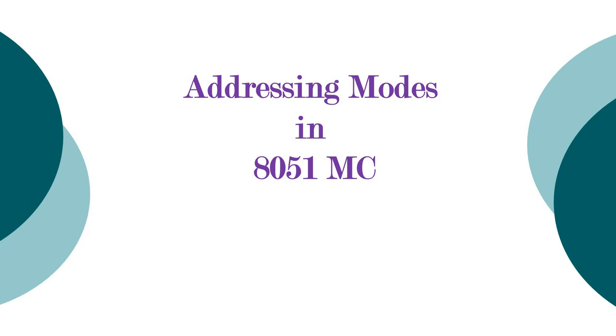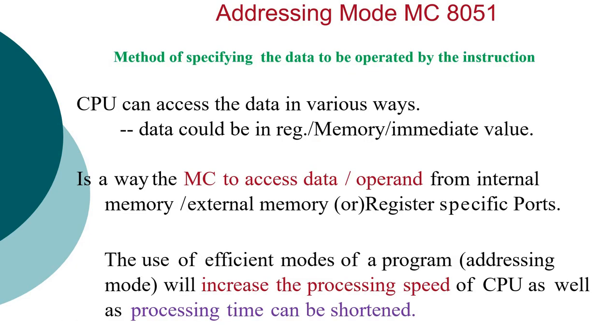Today we are going to discuss the addressing modes in 8051. It is nothing but the method of accessing the data which is to be incorporated by the instruction. It could be accessed by the CPU or by the microcontroller. But whatever the mode of operation, if it is a process of specifying the data by the operand of the instruction, then we term it the addressing mode,